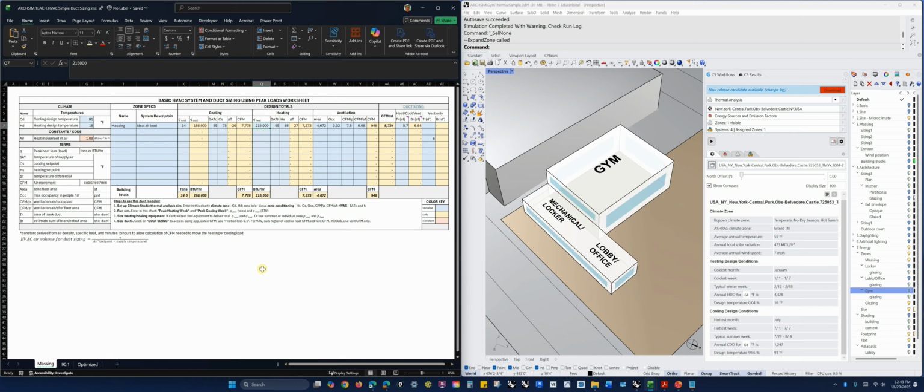So that's a lot of information. Maybe it's confusing, but I'm just trying to give you the reason why all these values are here, and that we're now going to pick the larger CFM from cooling, the 7,778 CFM, to size our duct. However, we also need ventilation, right? So we need more information before we can know how big the duct needs to be.